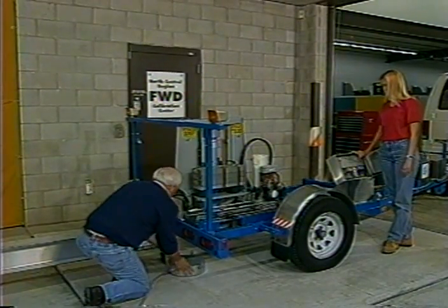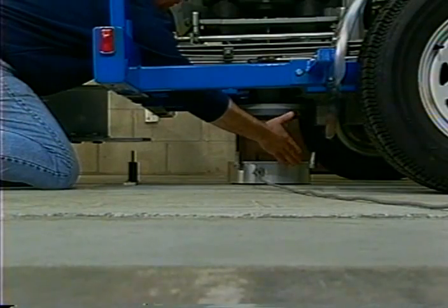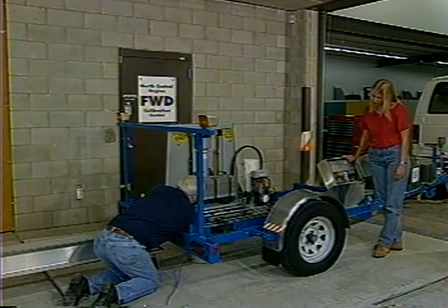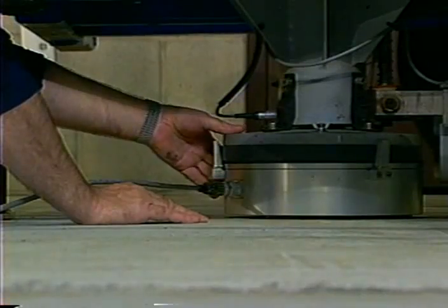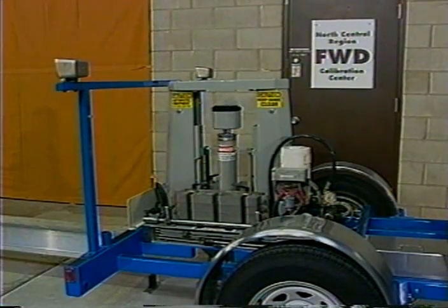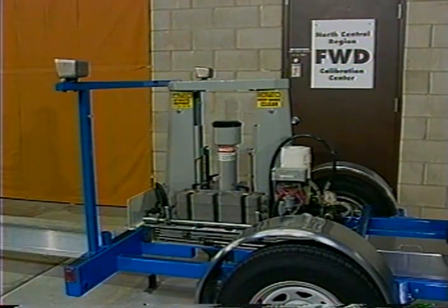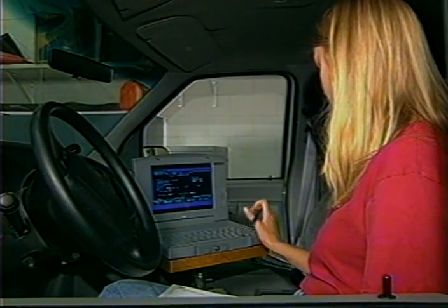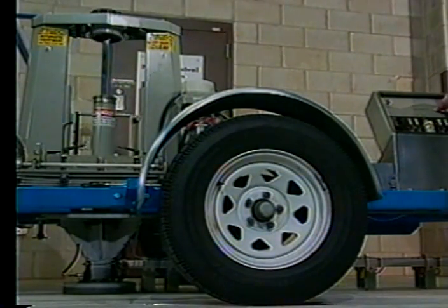The first part of reference calibration is to calibrate your FWD's load cell. The calibration center has a reference load cell that's calibrated annually to a national standard. Working together, you and the calibration center operator position your FWD's load plate right on top of the reference load cell. Then you go through a series of drops at 4 load ranges. You compare the output of your load cell with the output of the reference load cell. The result is a gain factor, a number that you key into your computer. From now on, every reading from your load cell will be multiplied by this gain factor.